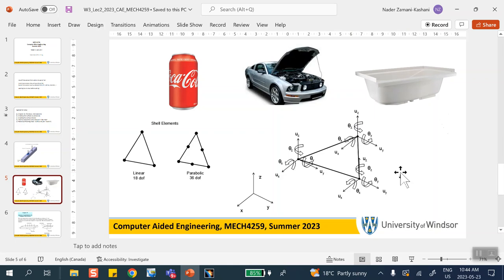Now, because these go on surfaces, obviously, you're going to need a surface. Now, there are different ways of creating those surfaces, and this course is not making you an expert in surface design, but you have to know some very basic processes in order to calculate the surface of an object. And there are different ways of doing it. It could be that you have a three-dimensional geometry, and that's given to you, or you create it in CATIA, and you want to extract the surface of that object. That's one way, we call it extract.